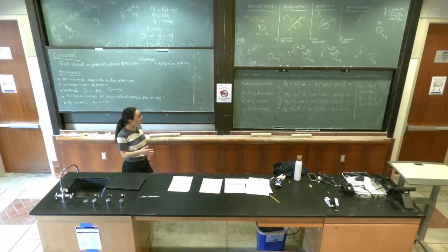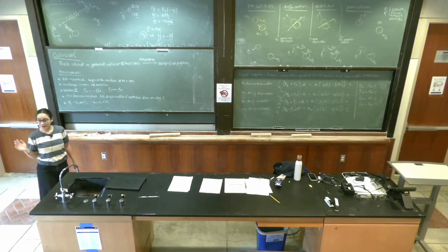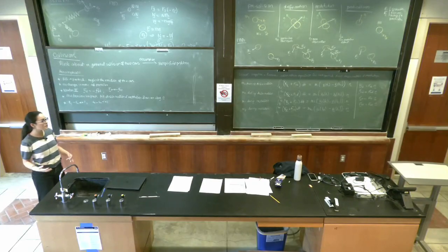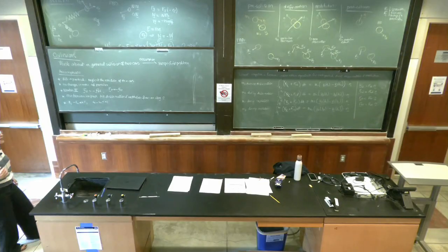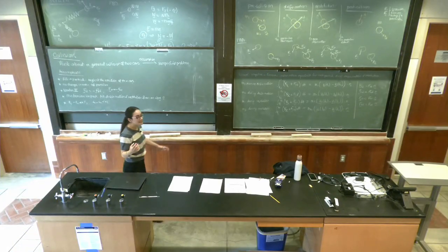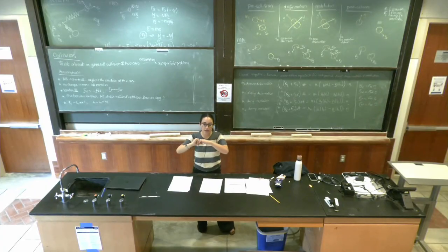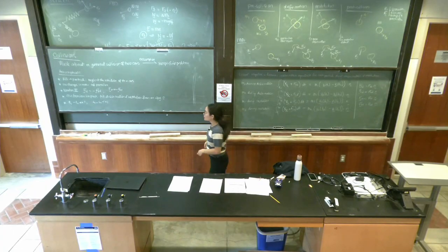Okay, so the linear impulse linear momentum equations are like this. I'm going to make more assumptions. So imagine how complicated this problem is. We're going to need to keep making assumptions so that we can make it into a manageable problem that we can solve by hand. Okay. The other assumption I'm going to make is that at T1, at maximum deformation, the velocities of the two particles along n are going to be equal. So at T1,